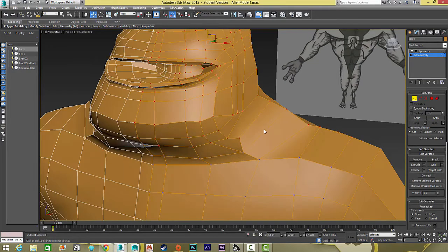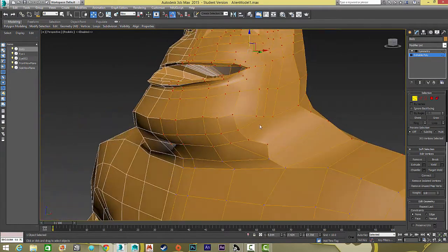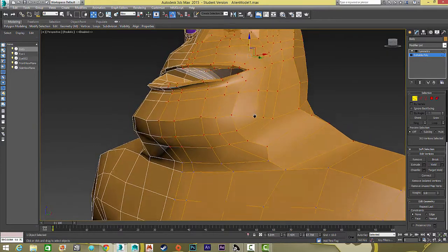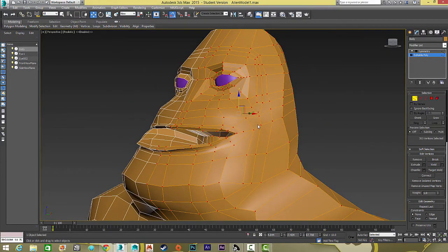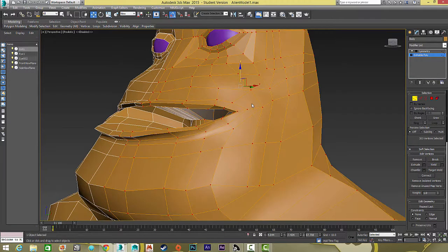We have to break the quad connection. There's still some triangles, but overall it's still a pretty good job breaking the triangles into triangles and then creating quads from that. So we want to create loops around the forehead all the way down to the chin. We also want some loops from the forehead down to the mouth and down to underneath the mouth. So we have loops around the mouth that should all be quads. Sometimes it just takes creating triangles and then breaking them back into quads.